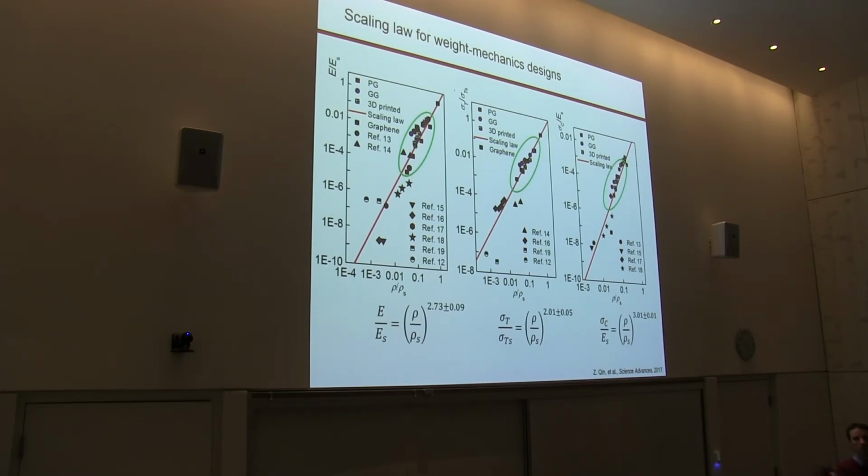Right now this gyroid is more like a homogeneous material, symmetric in all directions. But other minimal surface geometries can be more direction related, so they might have a strong x-axis but weaker y and z axes. Defining the objective function before optimization will be critical here.